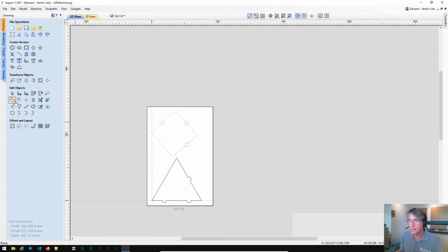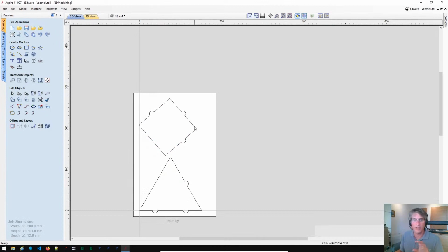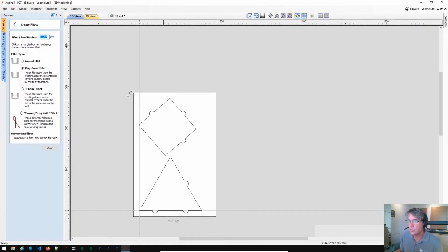all of that. So that's now basically, including the hinges, the shadow of our parts. But as I said, mustn't forget to fillet these corners too. So we're going to use a dog bone fillet. I've got a 1/8 ball nose, which is 3.125 millimeters, but over 2 because it's the radius we need. So that equals 1.5625, etc. And let's just bung those fillets in here.